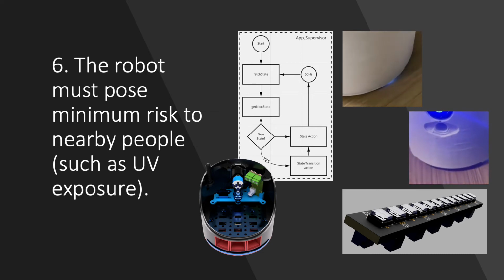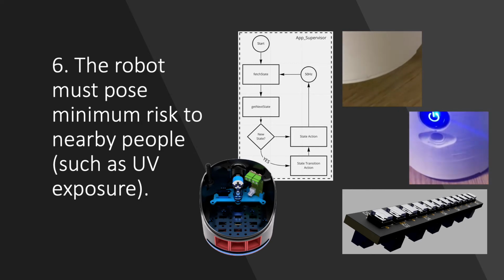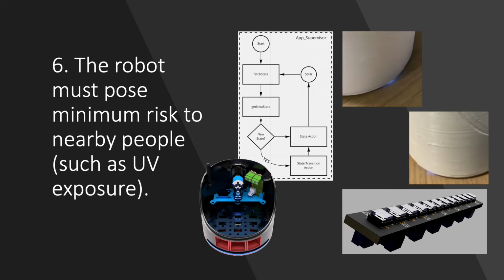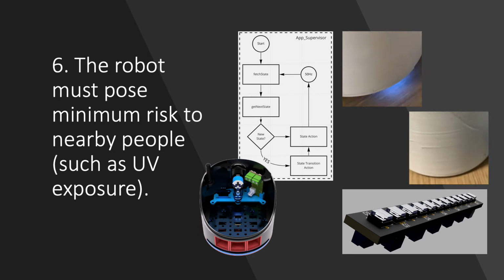This is done by checking the status of the IR sensors at the bottom of the chassis, or the IMU orientation readings. When these conditions are met, the robot goes into an emergency stop state that powers the UV off in hardware by toggling a pin connected to the circuit, which disables its operation. In addition, we have an emergency power shut-off button that kills the power to the entire robot.